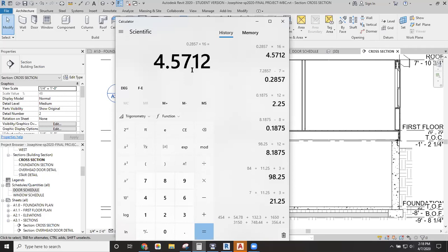Okay, and that's going to cause some variance in the top or bottom stair, right? It is, but you're allowed up to 3/8 of an inch difference from the tallest step to the shortest step. Okay, I'll give it a shot. I think that's pretty close to what you need right there, that it will work.